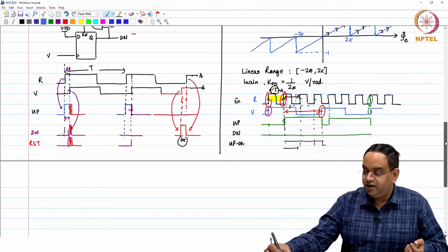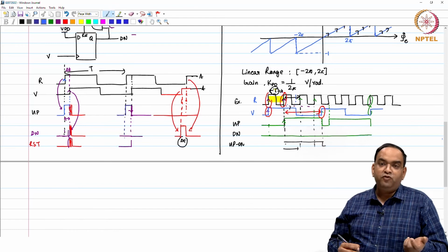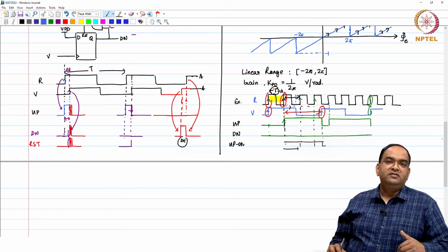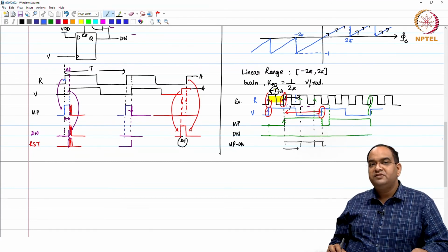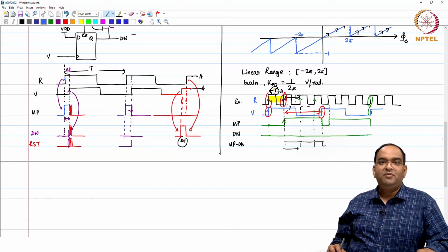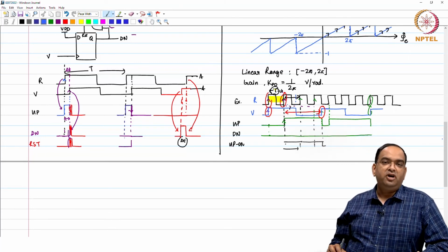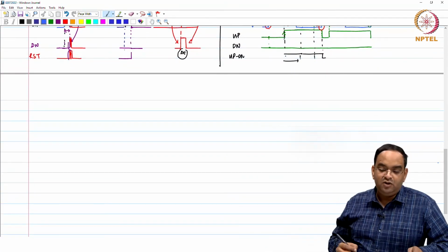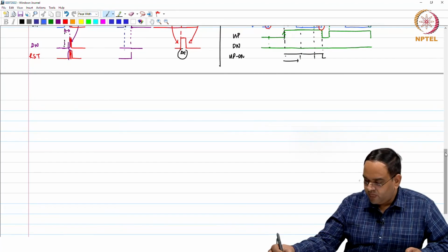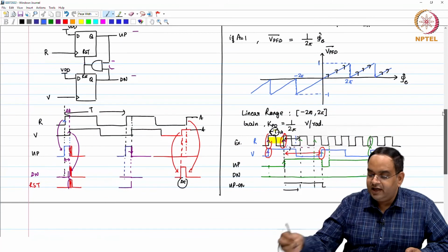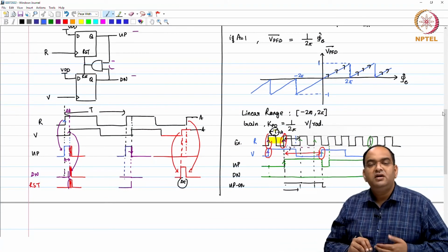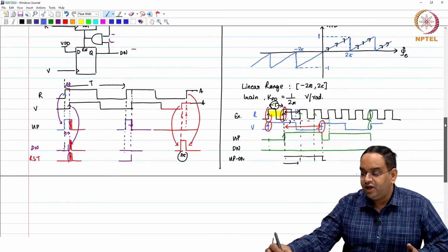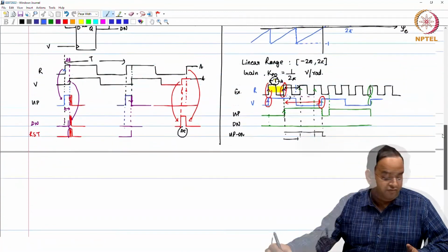So, this is useful for us to employ as a PFD, and do not worry about whether the phase detector will detect the frequency error in the given time and correct, and the PLL will lock. Those problems do not arise here. Okay. So, here what you see is you employ this PFD in your PLL loop, it will detect the frequency error and change the frequency in the correct direction always. Okay. So, that is about the phase frequency detector.